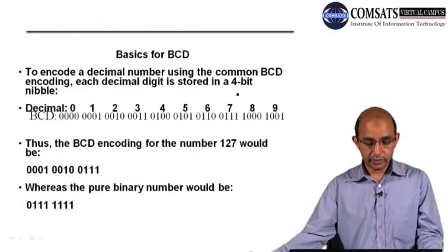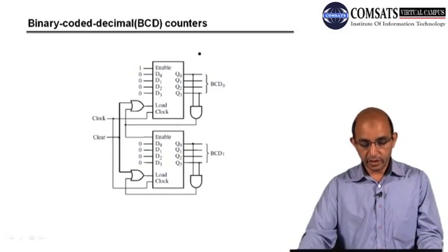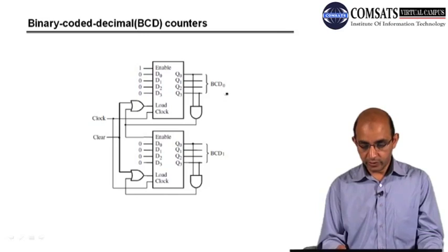Okay, so this is almost the same, and here we have the BCD counter. You can see that we have D's and Q's. So this is the enable, and this is the data, starting from D0, D1, and these are the Q's representing the output. You can see that this is the BCD counter, and it can count from 0 to 9.